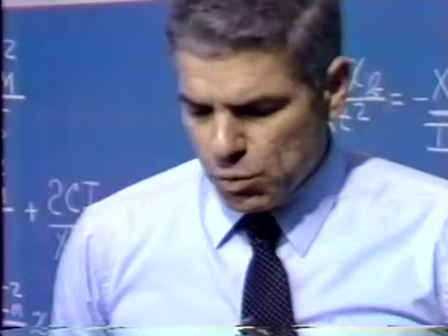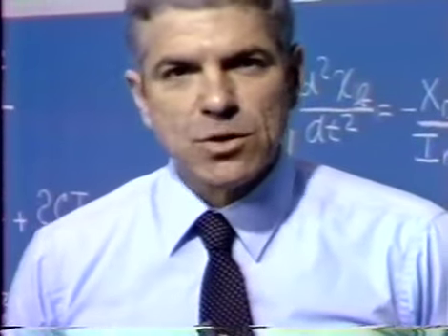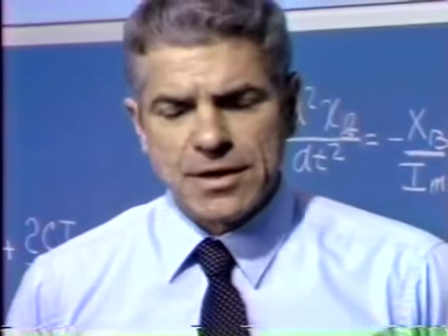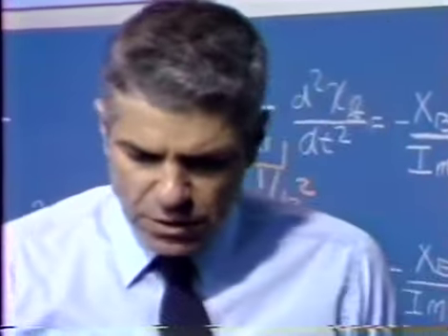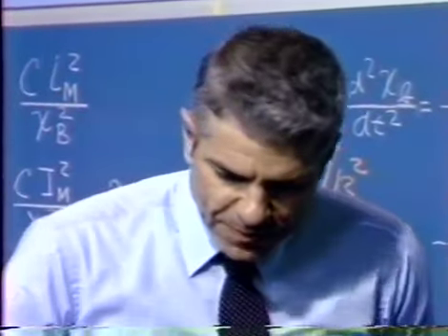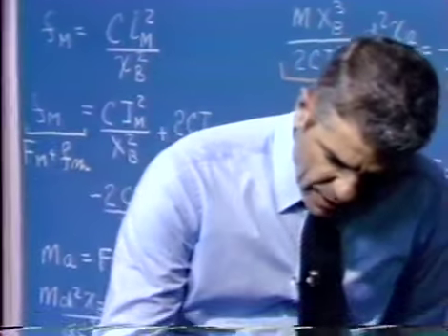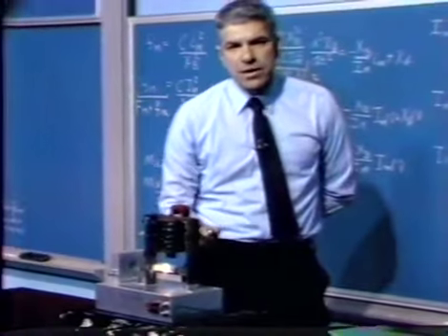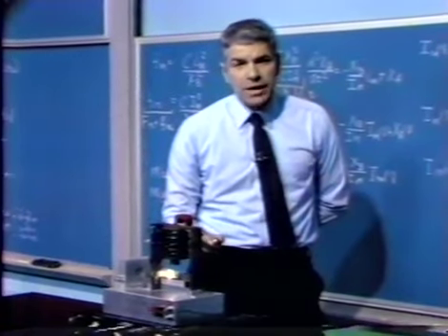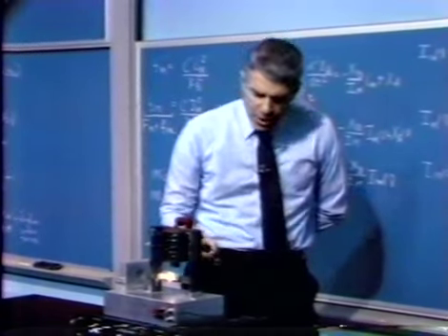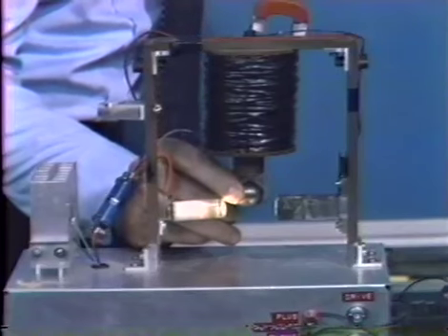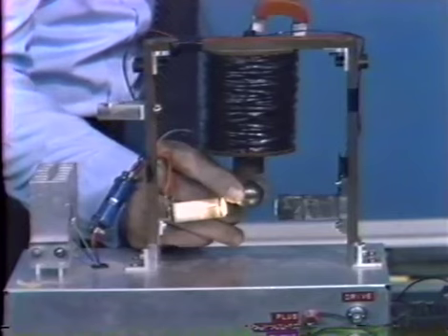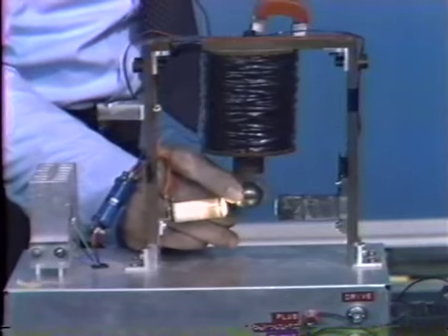And so what I did was adjust those variables, twist the pots, until finally I managed to get the ball stable in the magnetic field. In fact, what we can do as an aid to that, and that was actually the process that I went through, is even when the system's unstable, before we have the zero location and the value of A naught in the proper range, we can reach into the field, into the active area, close to the null position, and we can effectively feel the behavior of the ball.